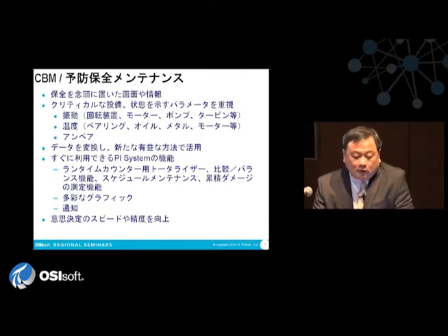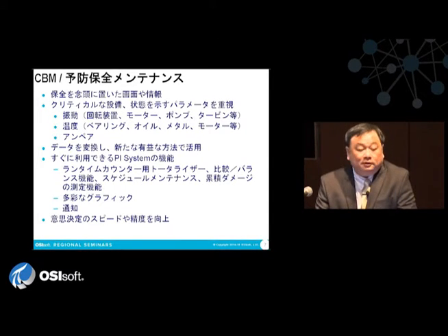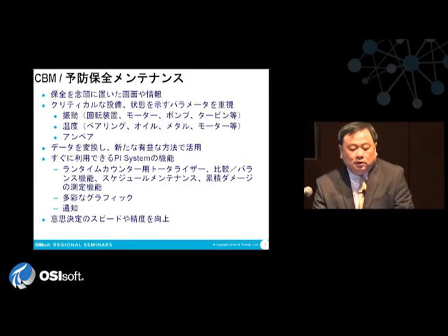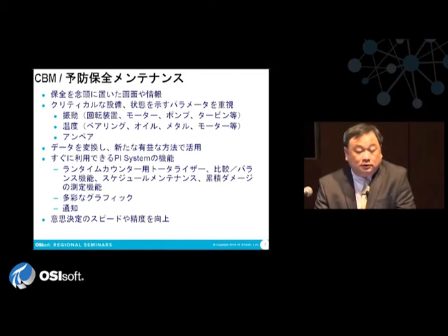So many people implement PI, and the first thing they want is a copy of a control room DCS display. This is good and very powerful, but the system should be used to develop specific visualization and information with maintenance in mind. Because the DCS display is always related to normal operation, very few with maintenance. So focus on critical equipment and parameters for condition: vibration, temperature, current.